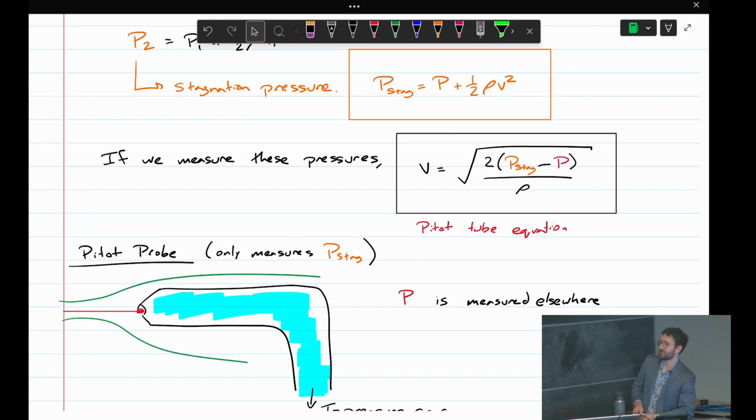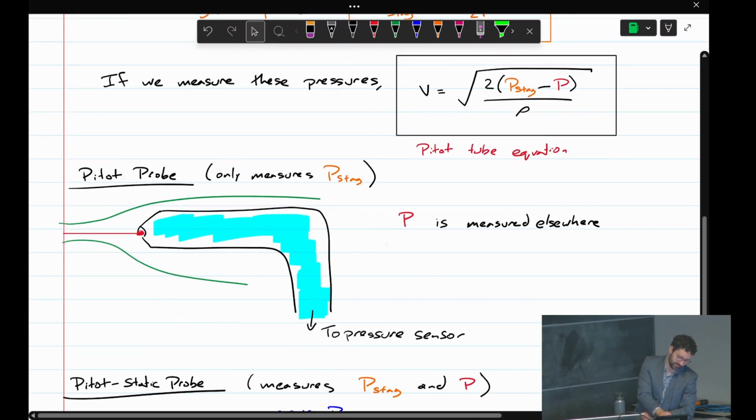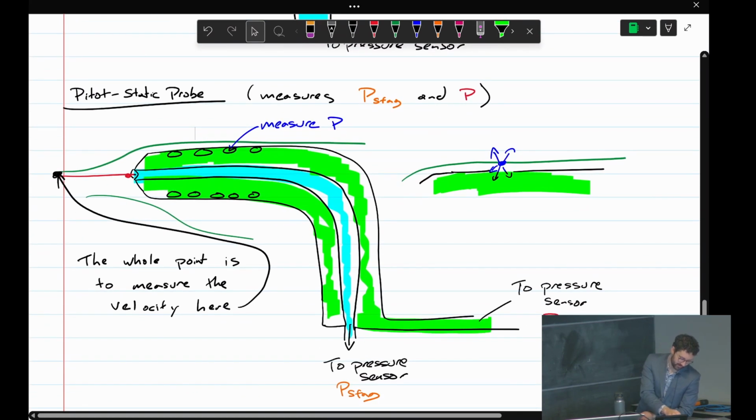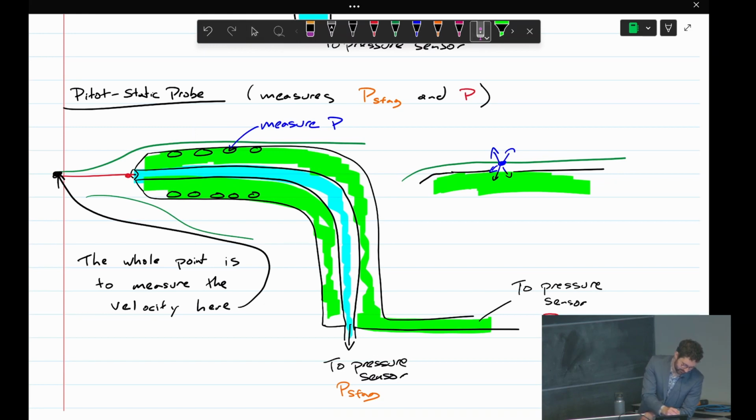Are there any questions about this pitot probe? Make sure when you're looking at that, you see the stagnation port at the very end of it. And also the very tiny holes here on the side are the static holes. Those I would say are probably the expensive ones to machine because that has to be a very, very nice finish. Any questions about pitot tubes?